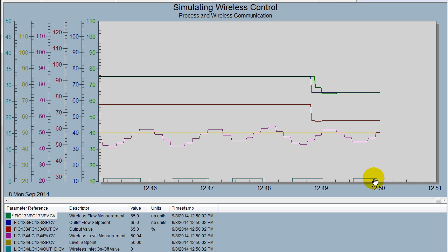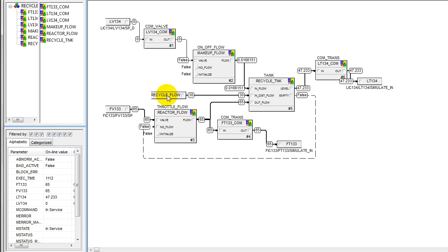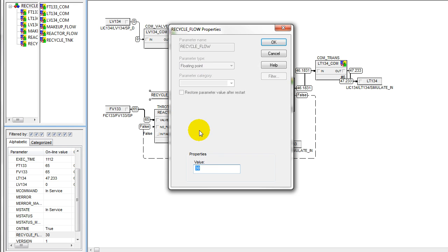We're taking less out, and therefore the level is reduced more gradually. What we see is that it takes less time to go from our deviation of 5% below level up to target due to the reduced pump out flow.